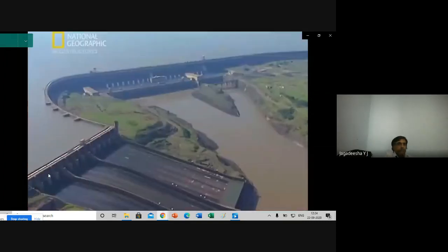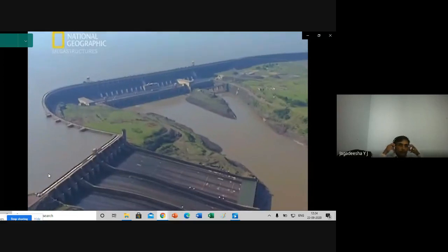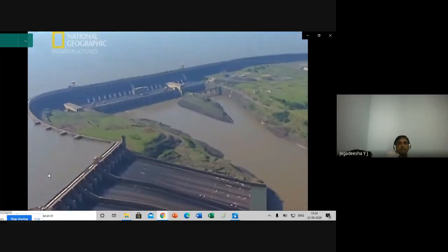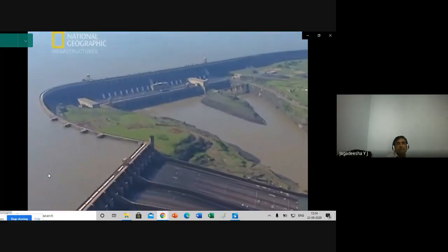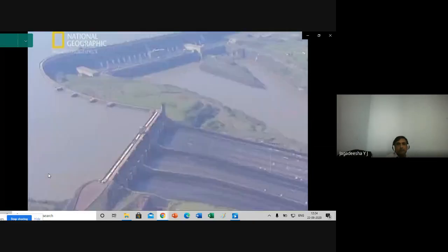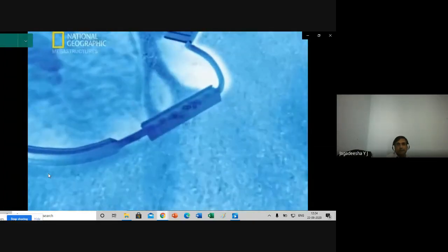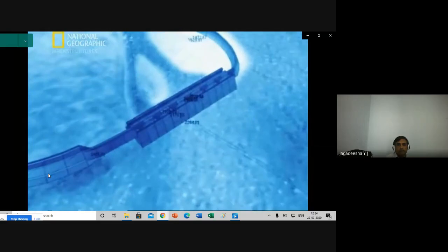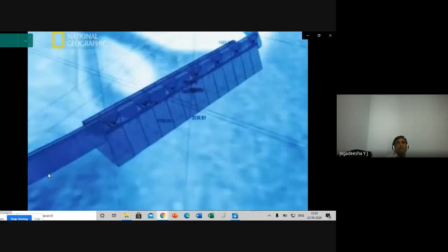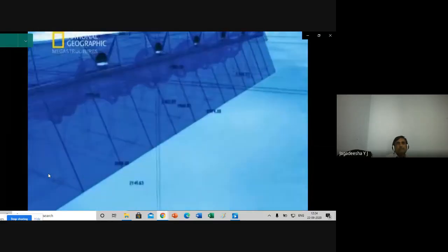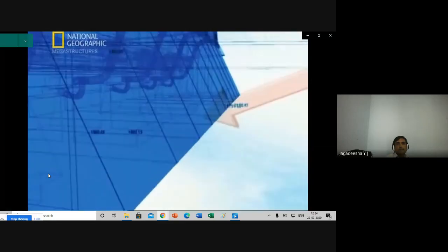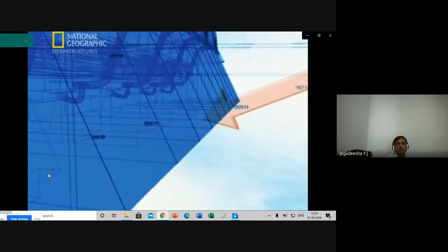But Itaipu has no such help from the terrain. It must stand alone. So Itaipu followed a design that relied solely on its own weight. Engineers called this a gravity dam. The idea was to make the structure so heavy, the water simply couldn't move it. To work, the dam had to weigh 61 million tons.